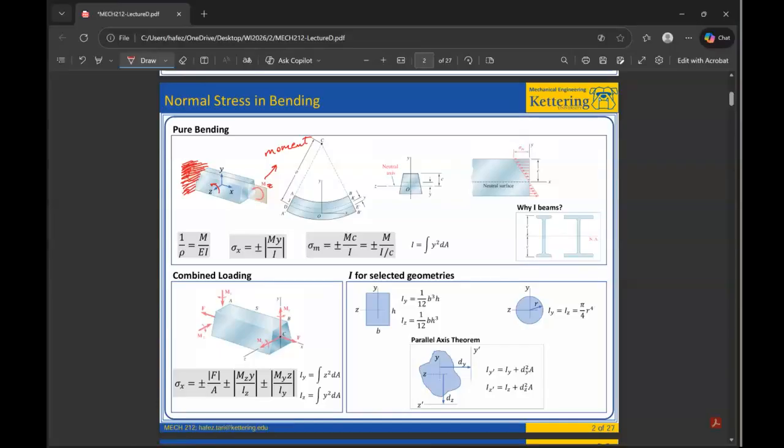All right. So what happens when we bend this? We bend this upward. It turns out that it follows this circular shape. So this segment that you see, it seems you're not able to see the cursor moving, but I'm referring to this shape. It turns out that it becomes a sector of a circular curve with the radius rho that is shown there.